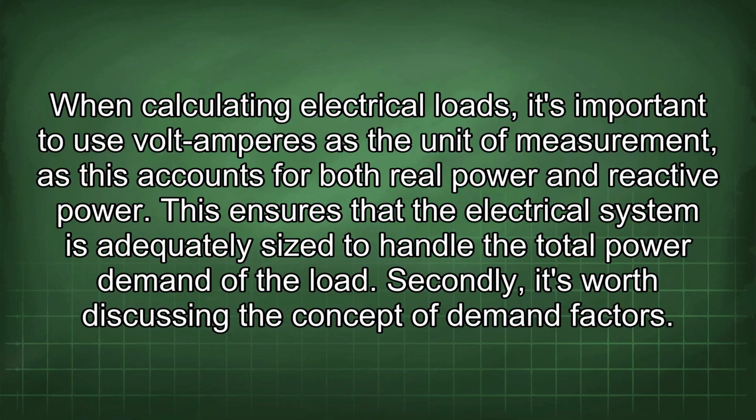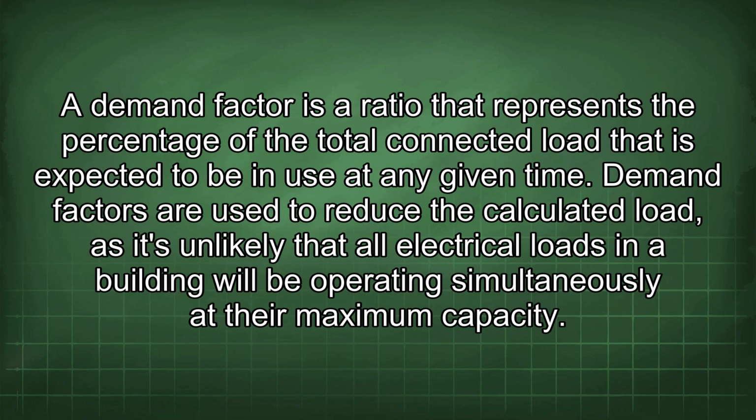Secondly, it's worth discussing the concept of demand factors. A demand factor is a ratio that represents the percentage of the total connected load that is expected to be in use at any given time. Demand factors are used to reduce the calculated load, as it's unlikely that all electrical loads in a building will be operating simultaneously at their maximum capacity.